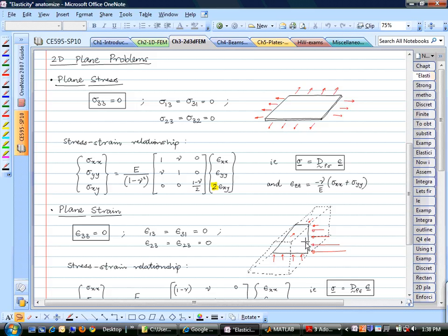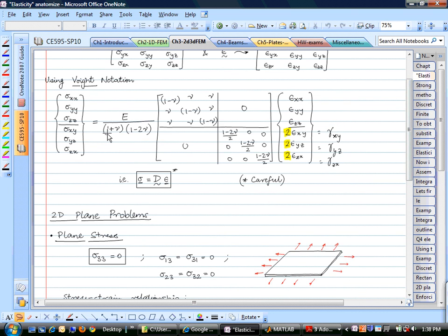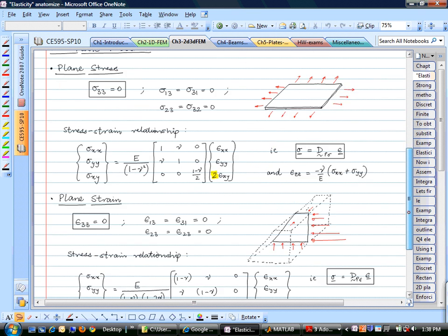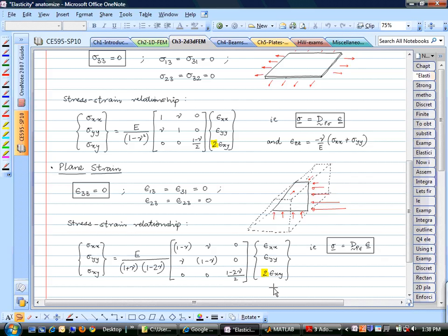So displacements are all constrained to be in this plane, and that immediately means that the strain in the 3-3 direction is going to be 0. So those kinds of problems are called plane strain. And we saw that if you specialize your three-dimensional elasticity matrix using these two assumptions, you can write out a new constitutive law for the plane strain and the plane stress cases.